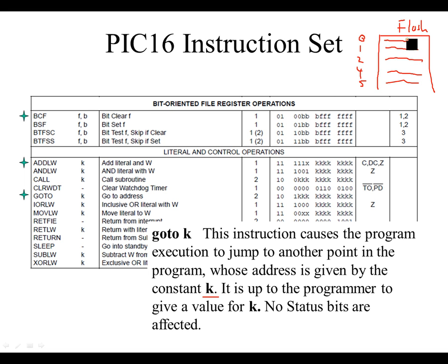opcodes or machine codes in here, and they start at 0, and program execution just increments the program counter. The program counter, the PC we call it, is going to point to 0, then it's going to point to 1. So you're basically going to step sequentially through this code until you get to something like a go to instruction or a call instruction, a sort of branch instruction. Certain instructions will skip a line of code, and some of them will go to a different location.